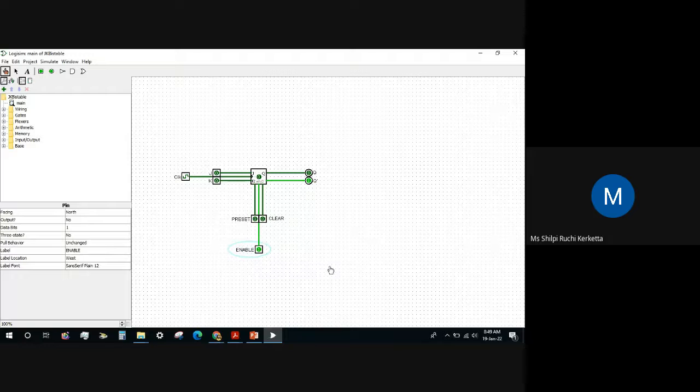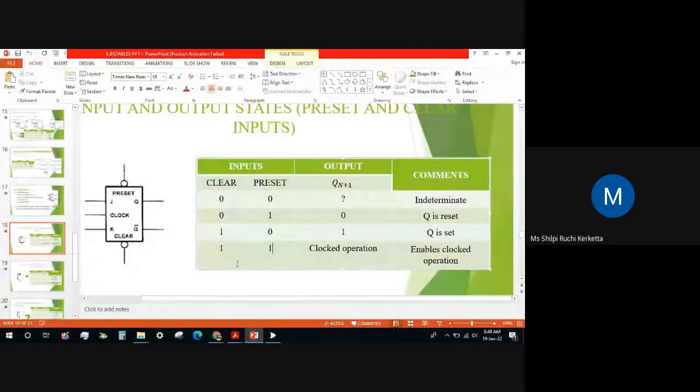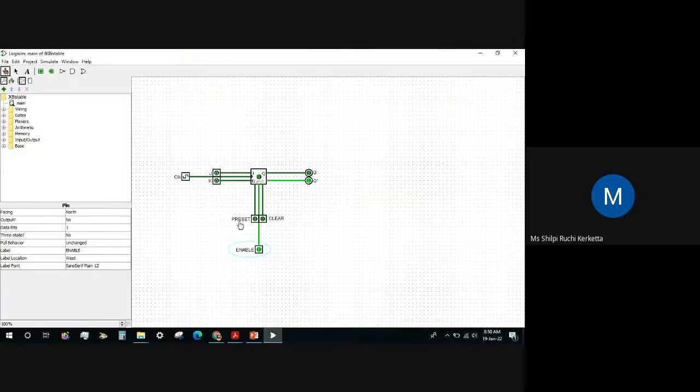Okay, so this is how our JK flip-flop is getting switched on. If we put this condition as 1, 1, our JK flip-flop is getting switched on. Because this is negative edge triggered, we will use the condition of 1, 1. And because this is positive edge triggered, this is not in your syllabus. This is for reference, and the IC we are getting here is positive edge triggered.